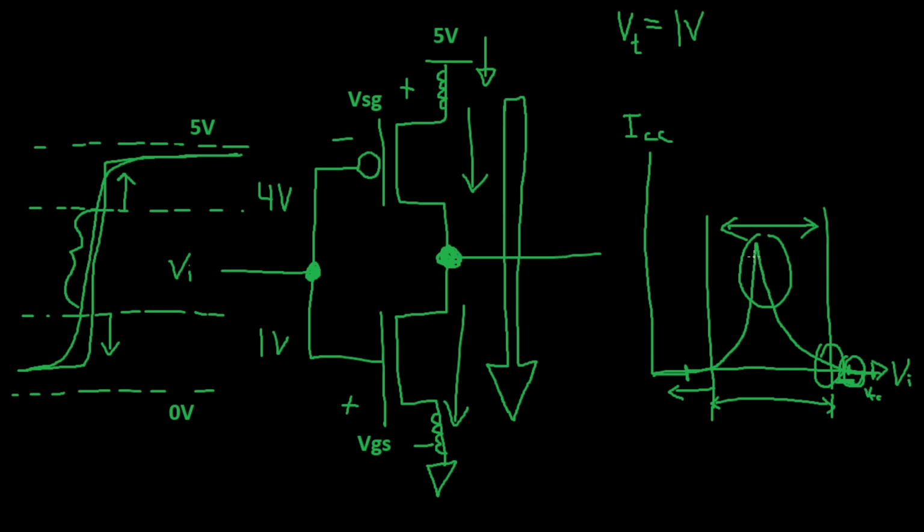When your input threshold shifts, the output can change states, and this can happen repeatedly very quickly and produce oscillations. In more complex logic devices, you may not even see those oscillations at the output. It may only be internal to the device. That's going to draw additional power because every switching event causes more power to be drawn, and it can cause the device to operate incorrectly.